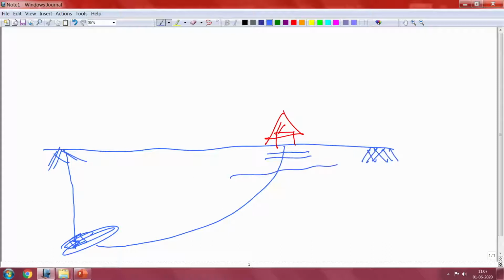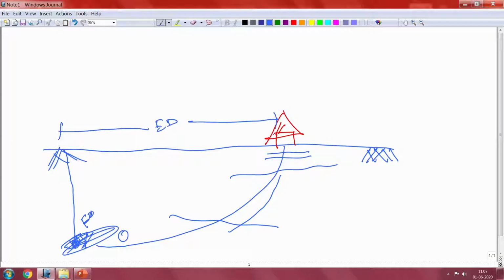Then followed by your rock will keep on increasing with a different rock. So, this particular rock, where the rupture is taking place, this is actually a focus. So, this is the focus and this is basically your epicentral distance, and this one is basically your hypocentral distance, and this is basically your H, depth of the earthquake.